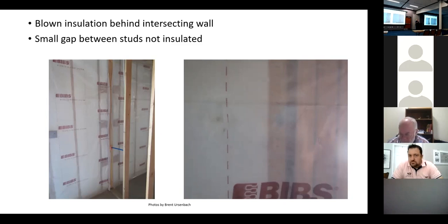But you could put a vapor barrier on and you could tape the vapor barrier to all the boxes. You could caulk all the electrical wires going into the boxes. And if you didn't damage it, then you'd have a good vapor barrier and that'd prevent water from getting into the walls. But if you don't do all those things, and if you make sure you prevent your drywaller from using routers, then maybe you can have an effective vapor barrier.